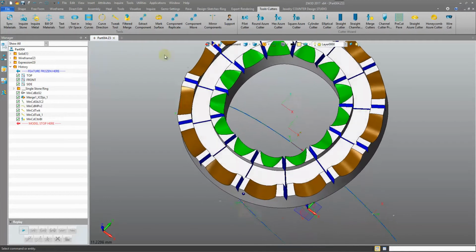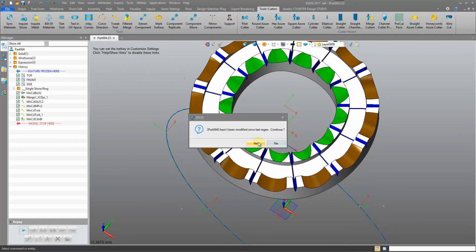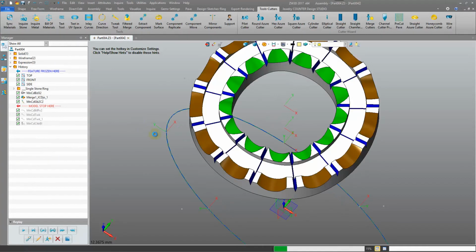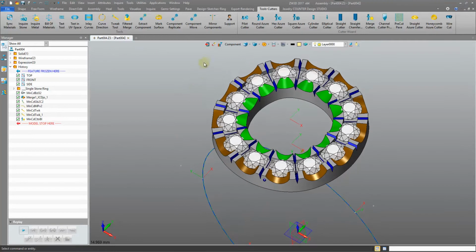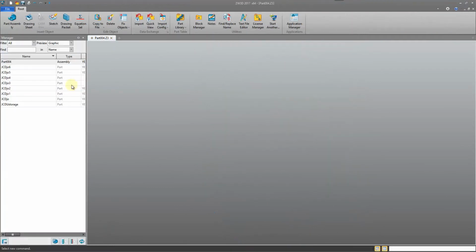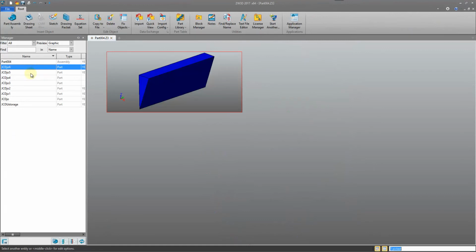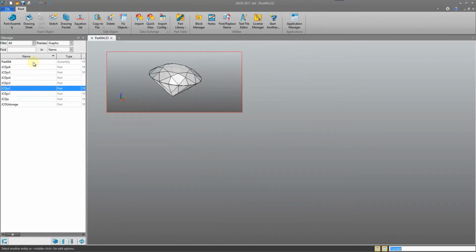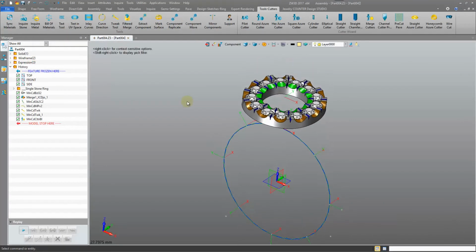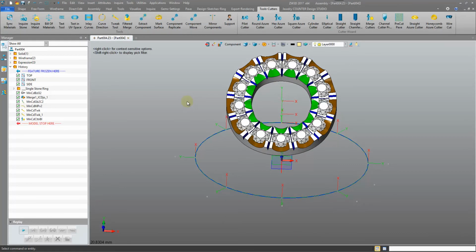All of our components are gone, and then I just regenerate, and the software will bring back only the components that I used. It won't bring back all of our tweaked variations. If you now exit back into the root, you'll see that there are fewer parts. So that's just something to be aware of if you ever notice any funny behavior, but if you follow the right strategy, you shouldn't need to do that.